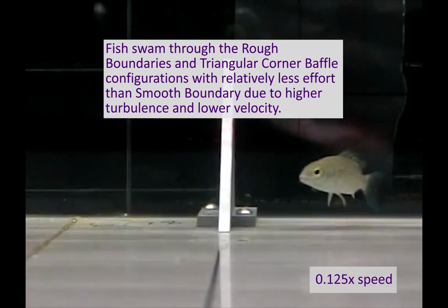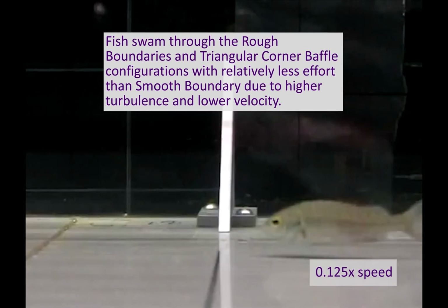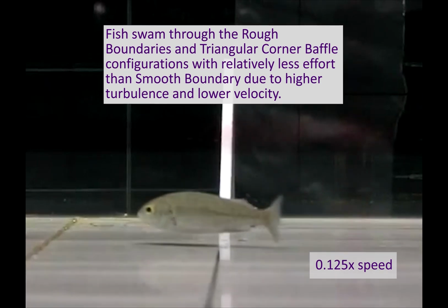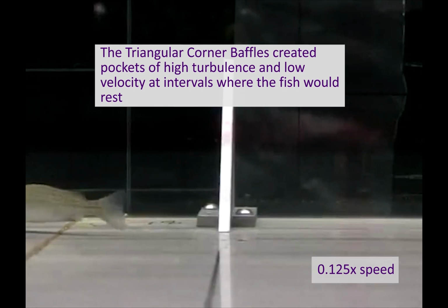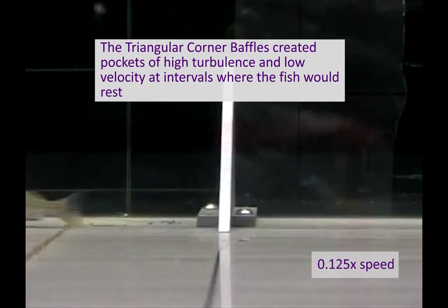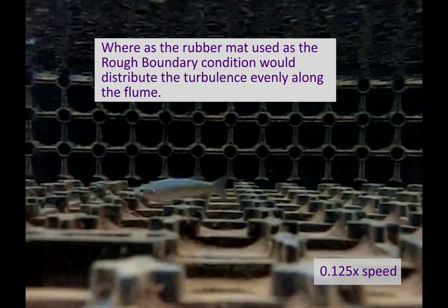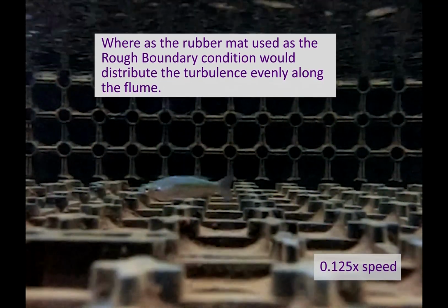Fish swam through the rough boundaries and triangular corner baffle configurations with relatively less effort than the smooth boundary due to higher turbulence and lower velocity. The triangular corner baffles created pockets of high turbulence and low velocity at intervals where the fish could rest, whereas the rubber mat used as a rough boundary condition would distribute the turbulence evenly along the flume.